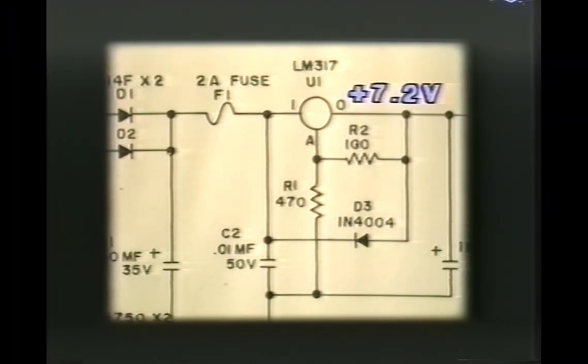Here the regulator is drawn as a circle instead of a rectangle. You might even see a 3-terminal regulator schematic drawn as a triangle. The decision to draw the 3-terminal regulator as a rectangle, a circle, or a triangle is really arbitrary, and it's up to the draftsman who draws the schematic. The output voltage of the regulator is determined by these 2 resistors, and by changing the value of these resistors, the output voltage of the regulator can be adjusted.